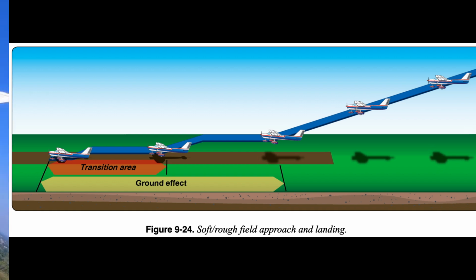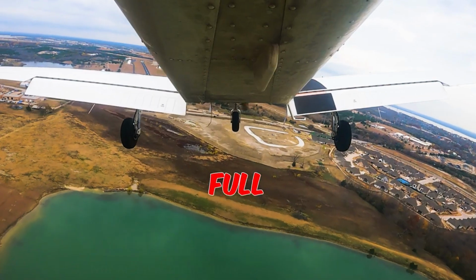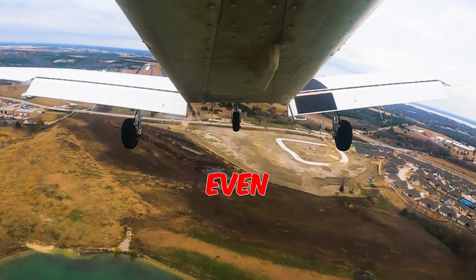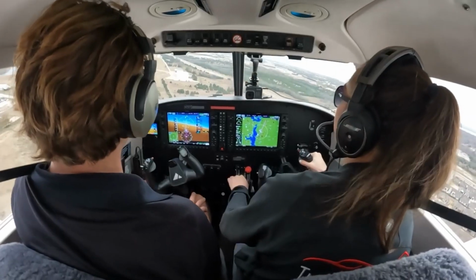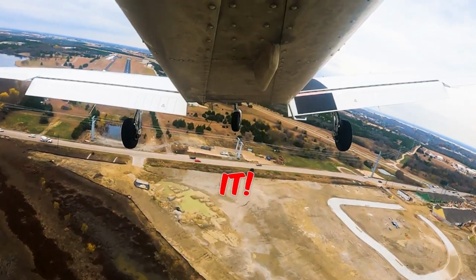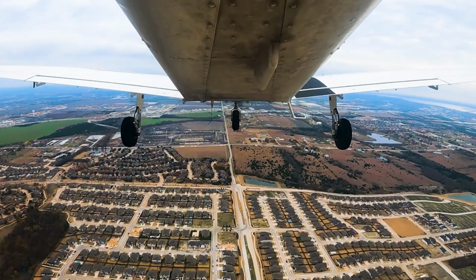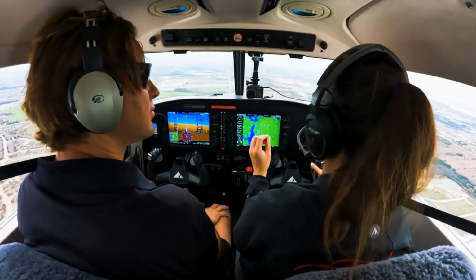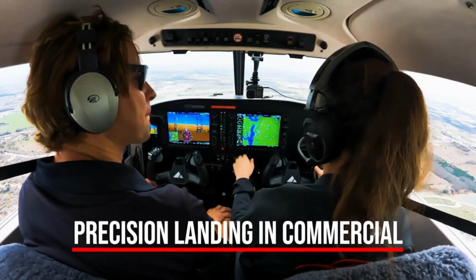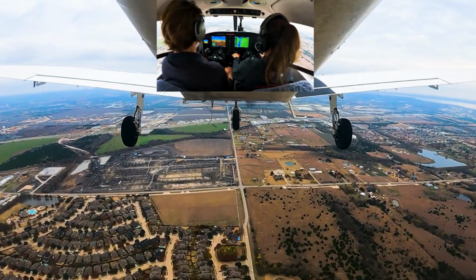Power-off accuracy approaches. Power-off accuracy approaches and landings involve gliding to a touchdown at a given point, or within a specified distance beyond that point, while using a specific pattern and with the engine idling. The objective is to instill in the pilot the judgment and procedures necessary for accurately flying the airplane, without power, to a safe landing. The ability to estimate the distance an airplane glides to a landing is the real basis of all power-off accuracy approaches and landings.